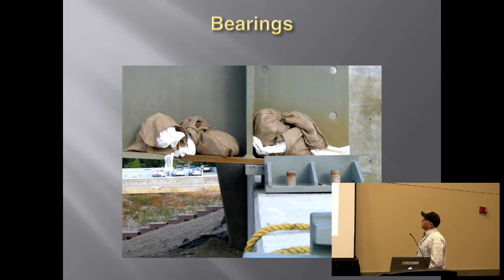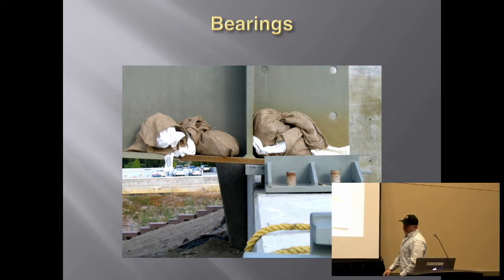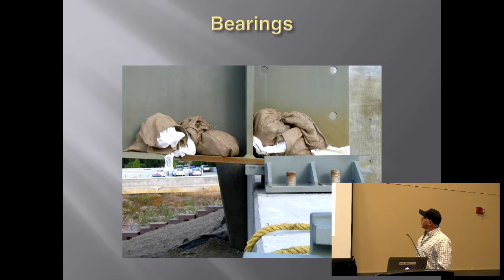On this one, the survey, there was a bust in the plans, and when we called and asked if the survey had been done, they said it had been and everything was right on. Well, we got out there and set the girders in place, and this is what we end up with. This girder bearing stiffener is supposed to line up right here. Of course, you can see the bridge isn't short. There was a bust in the plans, so they ended up coming in and putting a new stiffener in there.